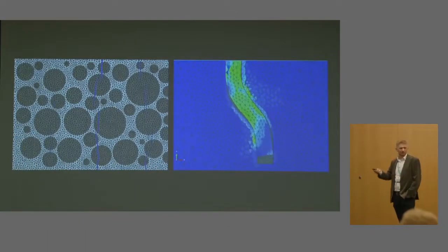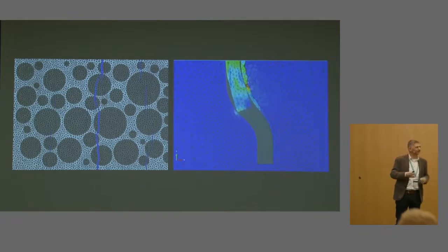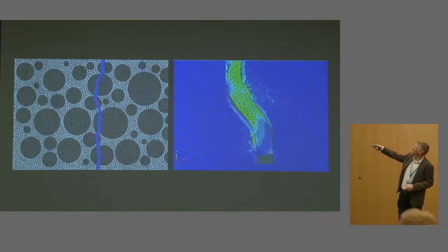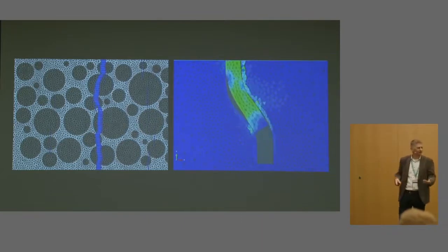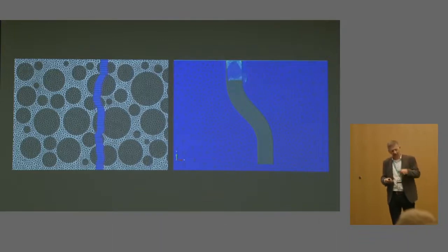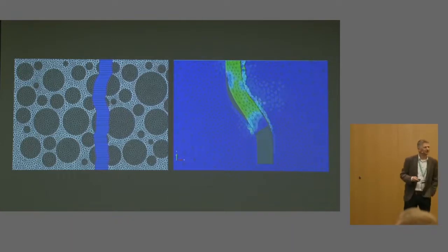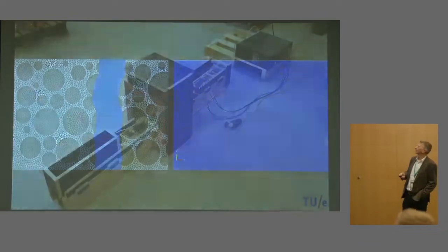And now my big trick with numerical concrete comes in, because what fiber I should use, I don't know. There are so many fibers, so many concretes. So what we do is have numerical models to pull fibers out of concrete. And by that we can see what shape of fiber, what composition of fiber, what material property of fiber with the concrete fits the best. So that's why we test that before we start to do our experimental test.